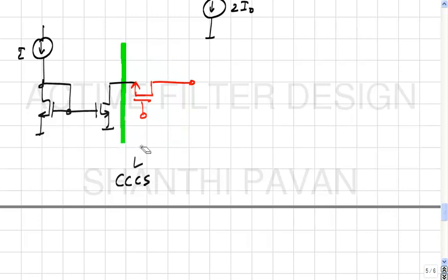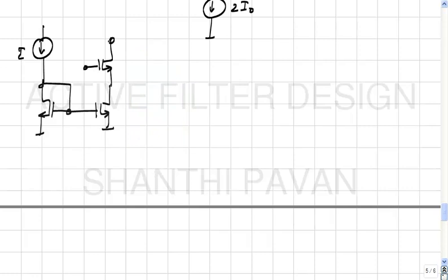Okay, so let's say I'm going to redraw the same thing. This is the current controlled current source, the device on top. It must operate in saturation. Let's say I bias the gate at VB. What is the lowest voltage this can go to? Let's assume that all the transistors are equal in size. What is the lowest this D can go to before the transistor goes into the triode region? VB minus...